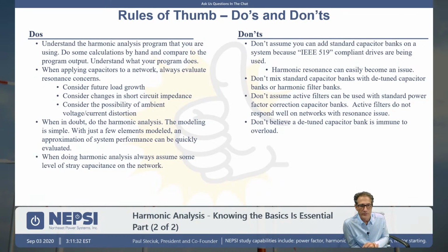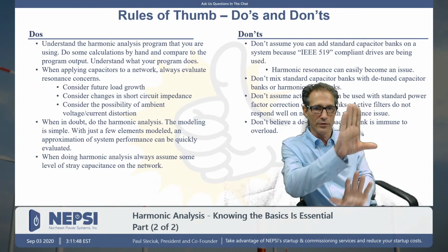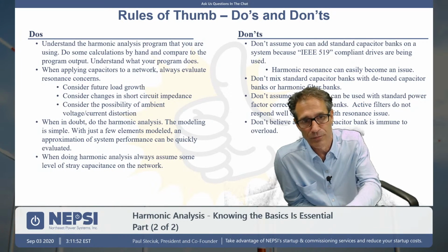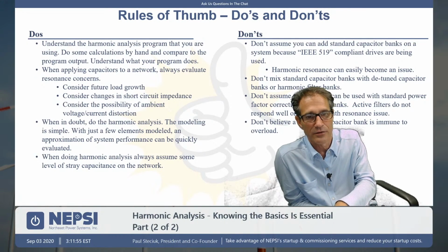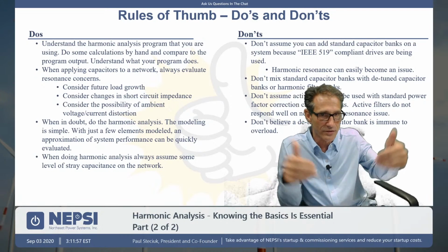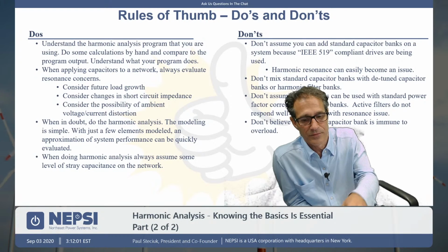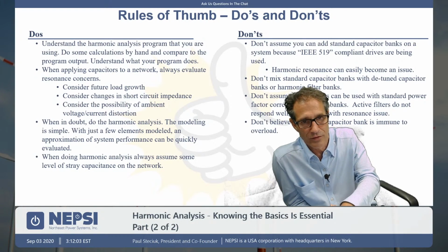So from our perspective, in all of our metal-enclosed solutions, we typically put the inrush reactor and the iron core reactor on the line side. The reactor is in series with the capacitor, and whether it's on the line side or the other side, it doesn't make a difference. There are some advantages to putting the reactors on the load side, and that is the voltage. If it's an ungrounded reactor and the system is balanced, the voltage to ground is less if the reactor is on the load side of the capacitor.